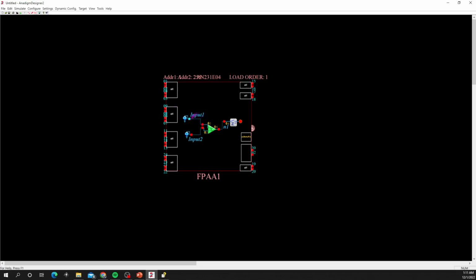Let's say I put one here and put another one. So here is another quick way. You see this little oscilloscope symbol. Let's just simply click it, and we have one more probe. Let's say we put it at the output, and then you can set up the simulation.